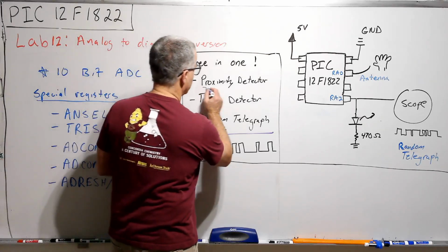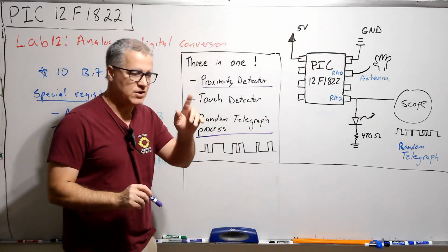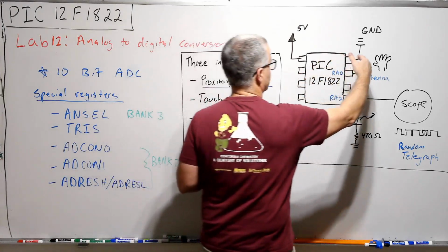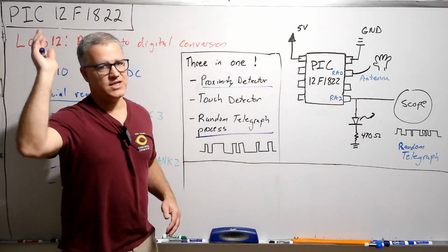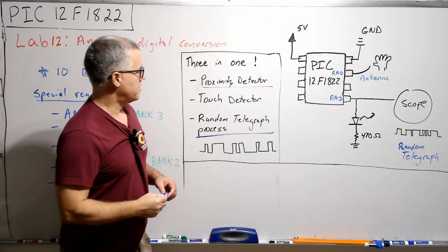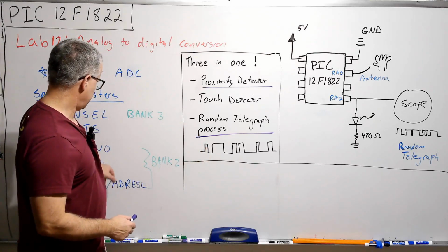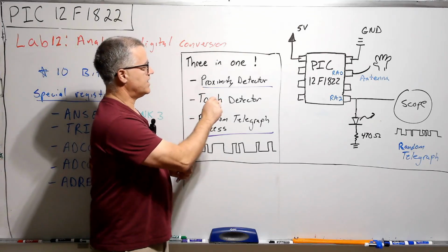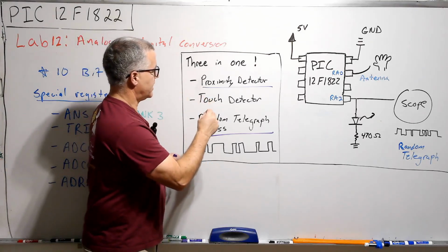We're actually going to use this as a proximity detector, so we act as a pretty good antenna. Certainly if we touch the wire, then the voltage basically swings all the way, and even if we were to use the most significant bit, the highest value, so up around 5 volts, we'd hit that often if we're holding on to it.